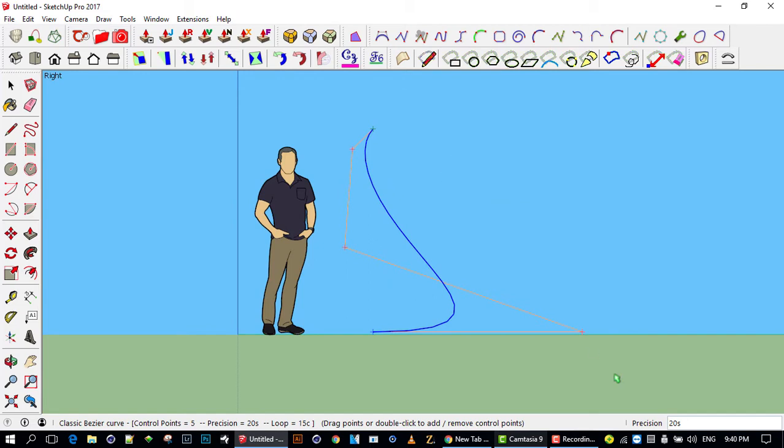But before I click that, if I look down at the bottom here, it says it's made up of 20 segments. I can now increase the segments, and maybe I'm going to say 50. Look at the curve, how it starts to smoothen off. Can you see that? If I go Control Z, you can see the curve here at the bottom is quite rough. If I go to 50, which is 50 segments, it smooths nicely over here. Then I click off it, and that's pretty much where it is.